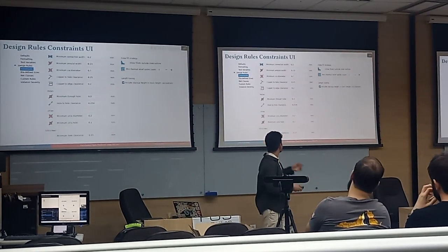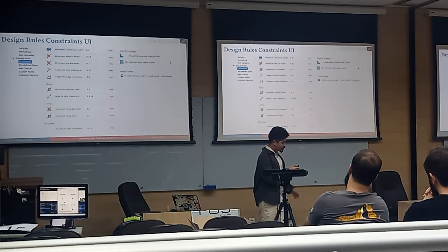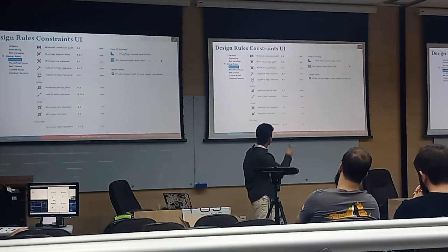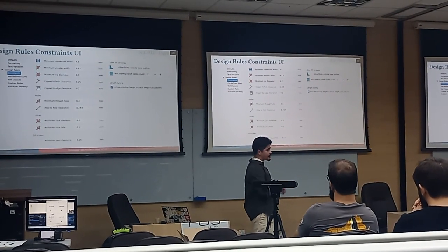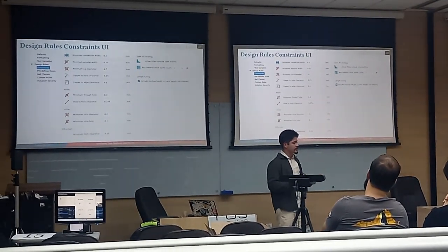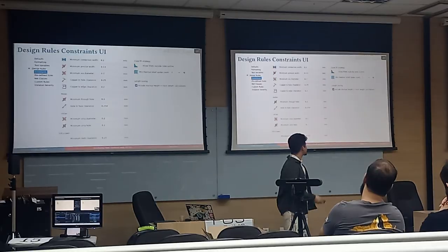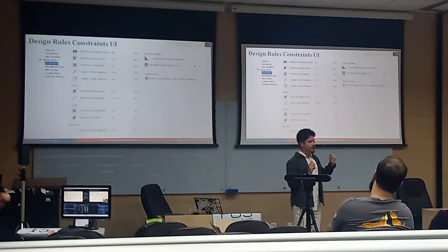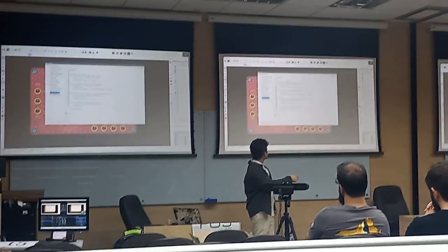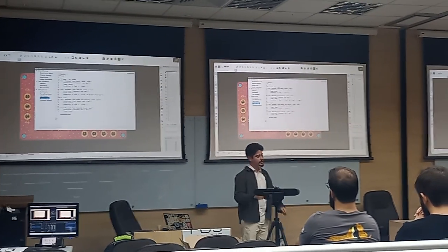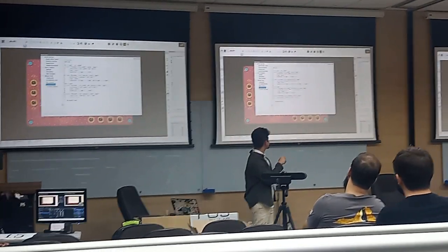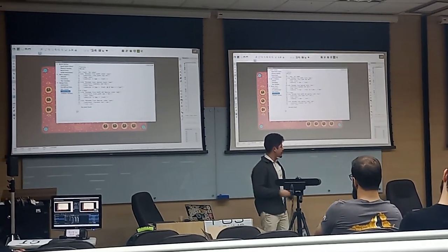For the geometric constraints that I mentioned, you can use a UI. It's very intuitive. You can just check, for example, the fabrication website or datasheet, put the rules in here, and you have a DRC working. If your process is way more complicated and you still want to use KiCad, you can make custom rules, which is not on the UI. This is the JLCPCB custom rules. For example, they have different rules for different layers, and you can just put this on your DRC and it will work straightforwardly.